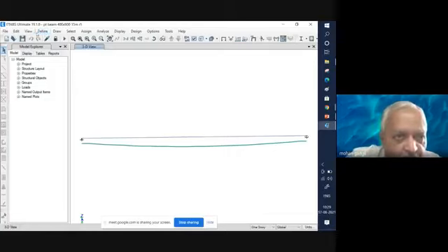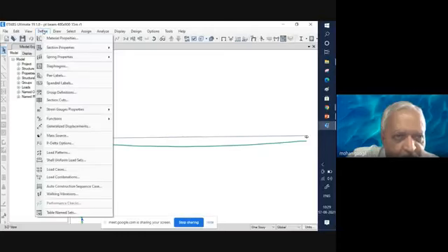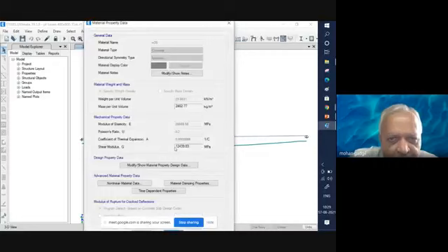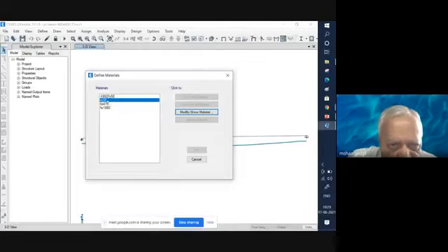Okay. Now, once you consider this beam, as you know, in ETABS you need to consider two definitions. One, you need to consider the material property. Now you have considered the material property of only three materials. Say the concrete that you are considering, this is M35 concrete, with its modulus of elasticity accordingly adjusted, 5000 root fck. So I have taken this particular concrete of grade M35. Okay, now that is my grade of concrete.